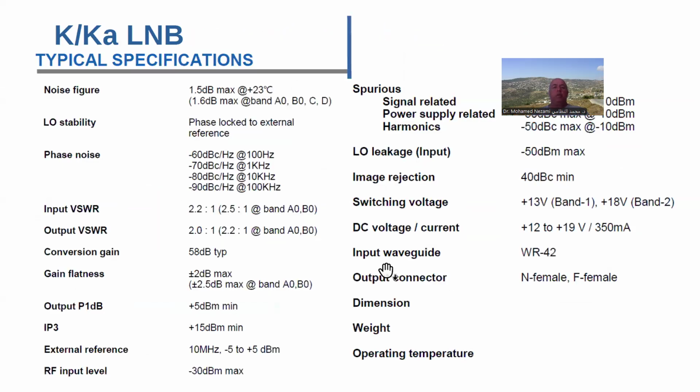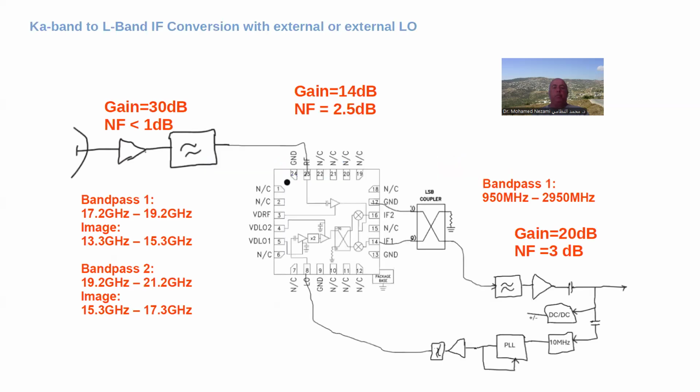Okay, so the mixer that I have chosen as a start right now, and in the previous session we went through a family of these. What I'm going to try to use is a single sideband quadrature down converter, which basically takes the signal in as an RF signal and splits it into two mixers that are driven with a quadrature local oscillator signal.